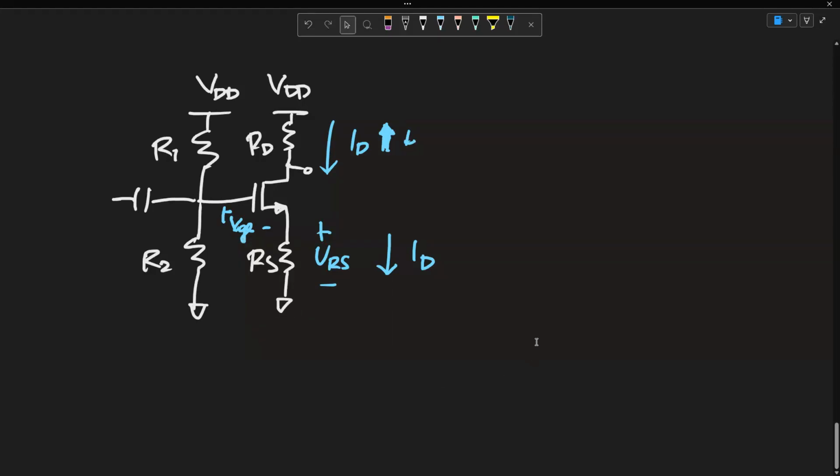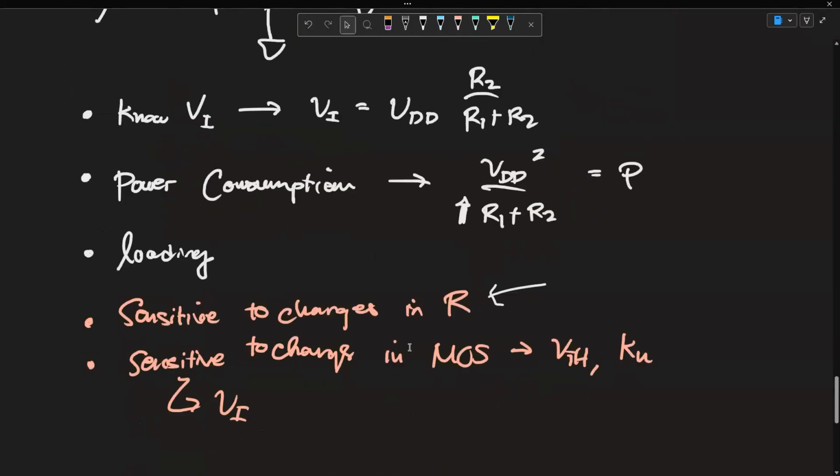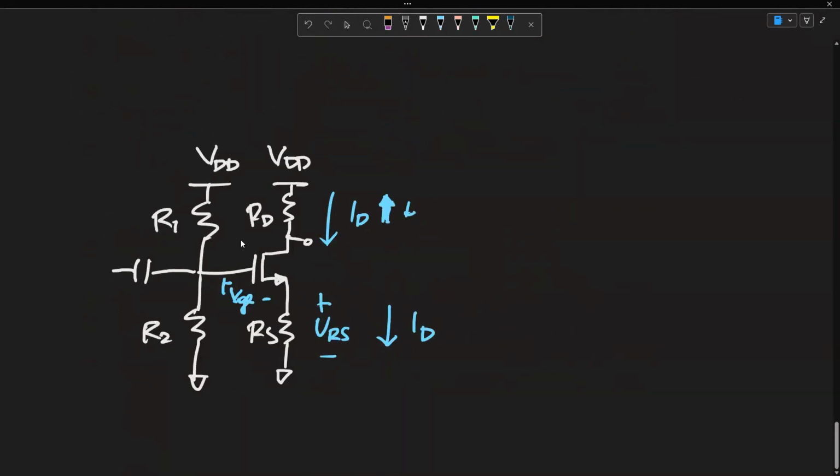But you'll see from small signal analysis na babawasan nito yung gain, no? But so that you don't lose your hair trying to pick the perfect MOSFET and so that it works when you show it to the prof, no? You usually do this kasi nakakaubos ng hair kumanap ng perfect MOS na tama yung parameters. Dito, it depends much less on the MOS and it depends much more on RD, R1, R2, and RS yung gain mo, no? So, does anyone have any questions about how this feedback happened?